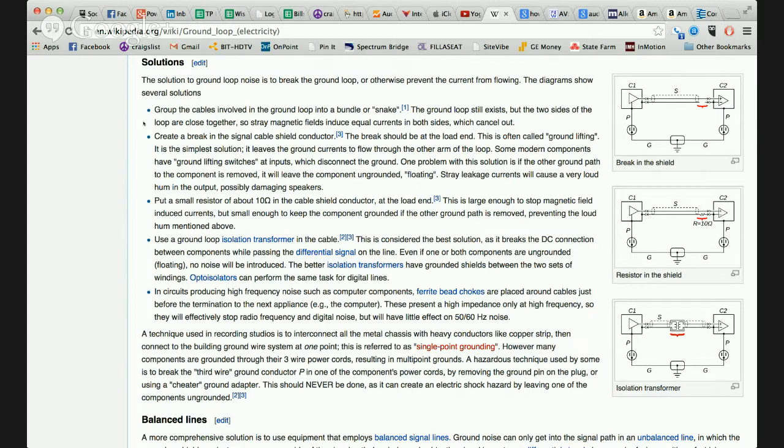And generally speaking, if you're running signal cable, okay, so in this case it'd be a mic cable next to a power cable, that mic cable, while it does have shielding and it does have technologies built into it that will allow it to reject a good portion of electromagnetic interference, or EMI is what we call it, it's not perfect.